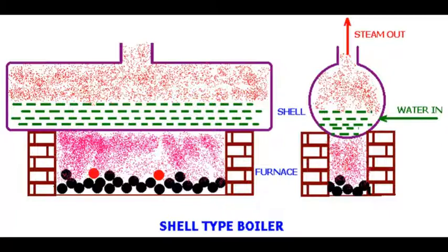These are mainly related to the area available for heat transfer because of the shell size, and there is more heat loss across the shell boundary, and there is no insulation surrounding it, and they are more prone to explosion as the shell is directly heated, and there are limitations on steaming capacity and on accommodating higher steam pressure. So that's why gradually they were discarded from service.